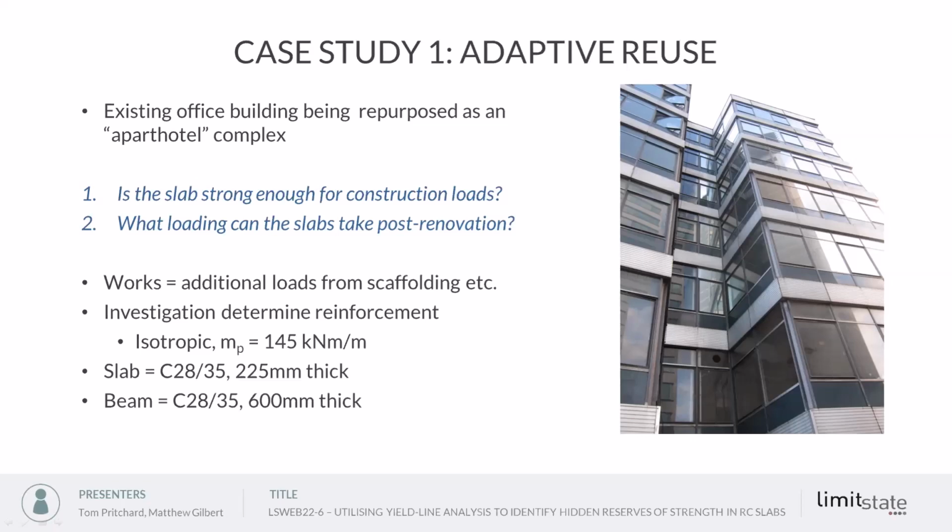So for this first case study, we're actually looking at an existing office building being repurposed as an apart hotel complex. It's actually taken directly from a client's case study, but the details have been anonymized suitably. So the two questions that the client was wanting to ask here are, firstly, is the slab strong enough to carry construction loads? And secondly, what loading can the slabs take post-renovation? And